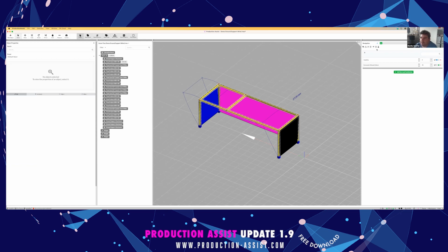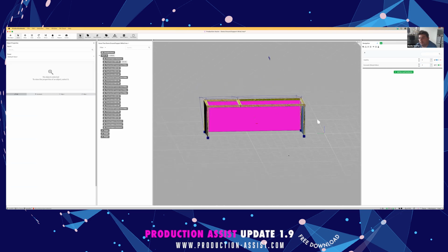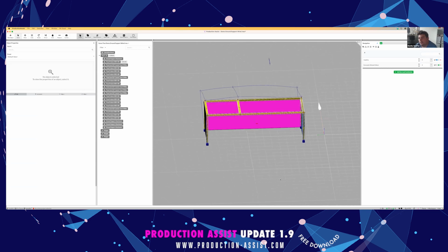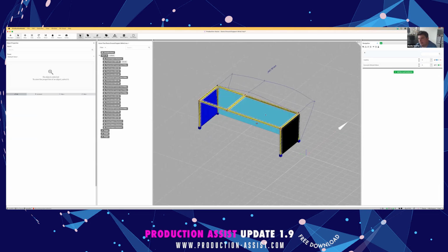One thing that we have added here, when you're now in the load combination, is that you can add the angle from which the load is coming. By default in here, I set it to 90. And if I change it, for example, to 0, so it comes from this direction, you see immediately it changes the way this has been calculated. Now these 2 planes are deactivated, and only the big middle plane is activated for wind load consumption.